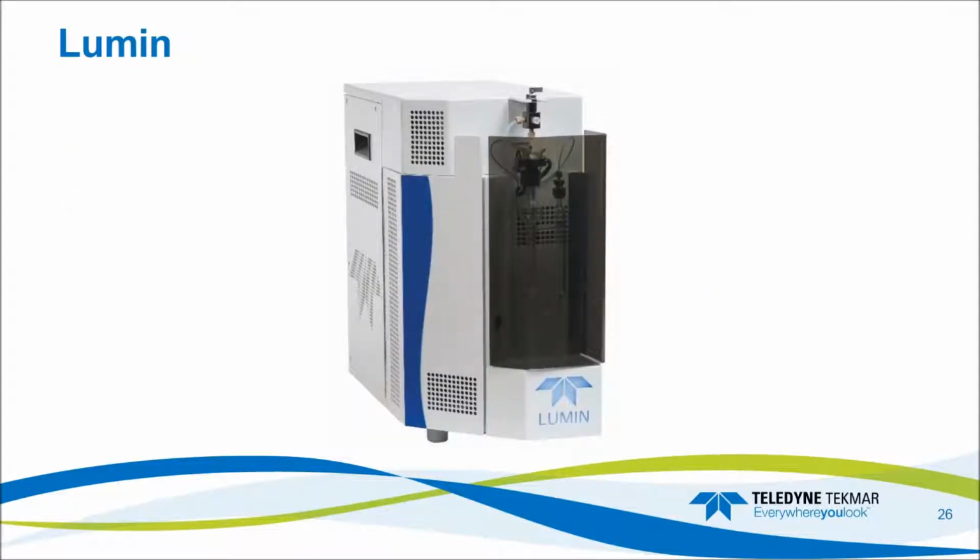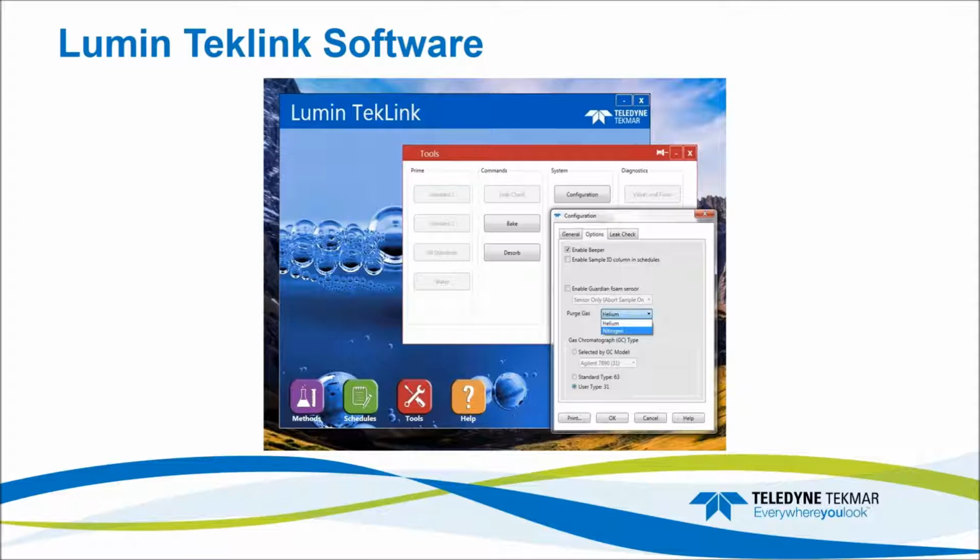So let's move on to some drinking water examples now, because when we talk about maybe slightly diminished purge efficiency, some of the concern that may come to mind is, can we reach the levels we need to see in drinking water? So for this example, we're going to look at the Lumin purge and trap concentrator. And again, it's real quick and easy to select our purge gas. We go to Tools, Configuration, and then we choose the Options tab of the configuration box. And then we have a drop-down menu where we can choose either helium or nitrogen. So in this case, we're going to use nitrogen.